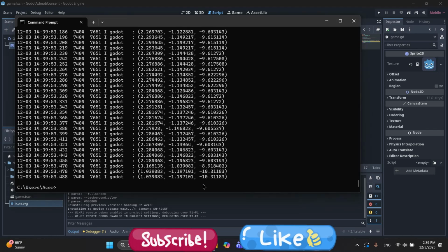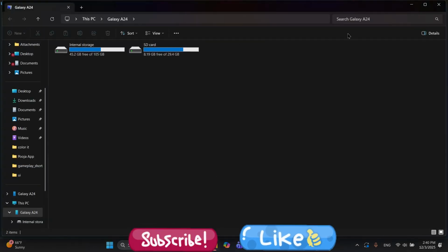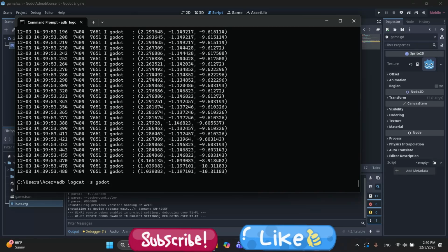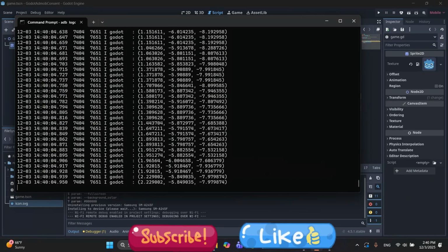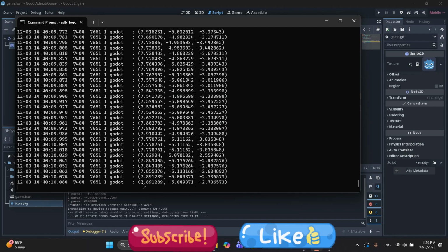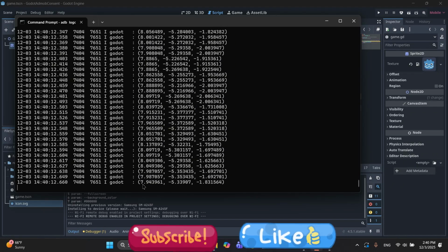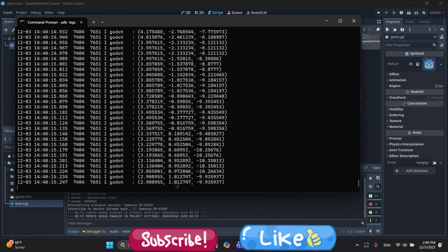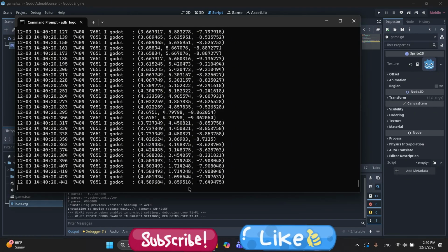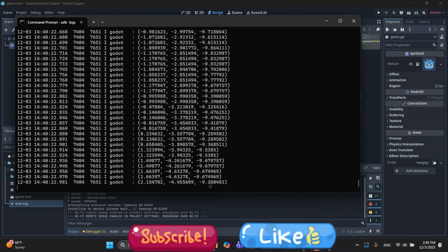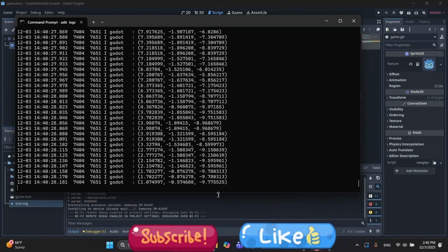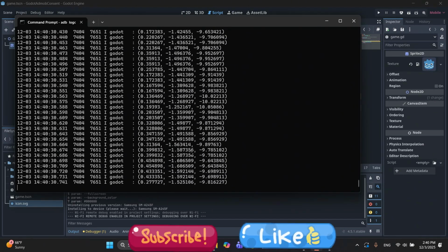So if I click my phone like this, what happened? Okay, my phone got disconnected. Let me run the thing again. Okay, you can see, look. I tilted my phone and you can see the changes in the numbers. It's tilting to the maximum value, 7 or 8, and here you can also see the change in the second component, 0, -4, 5, and in the third component you can also see the changes, -9, -10, like that. So that's the output from the accelerometer.